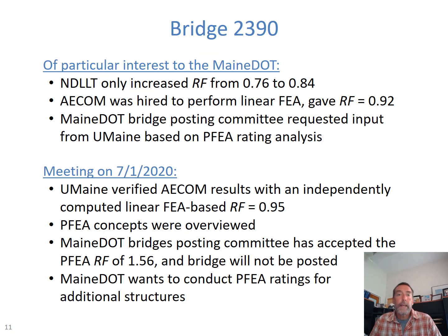Bridge 2390 was of particular interest to the Maine DOT. Non-destructive live load testing only increased the rating factor from 0.76 to 0.84. And they actually hired a consultant, AECOM, to do a linearly elastic finite element analysis and base a rating factor on that. And that gave an RF of 0.92.